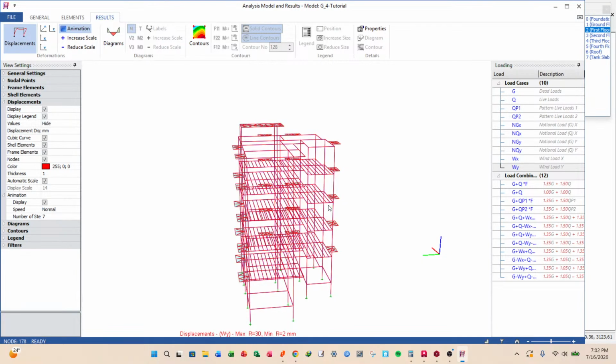reducing the sections where necessary, which may not apply here because all the sections we assigned are minimum, so we shall have to just increase the section properties where we have failures. We shall also reorient our columns in case certain dimensions become longer than the default dimensions and tend to compromise the architecture spaces.